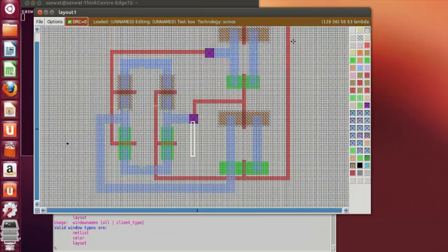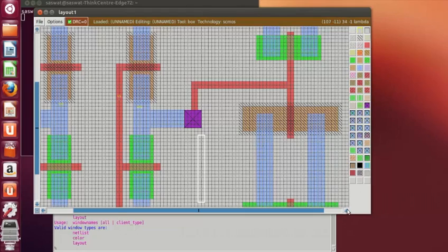Okay, this is connected to this gate. Actually, B is connected to this gate. B bar is connected to this gate. The opposite gates are connected. Then A is connected over here and A bar is connected over here. The output is obtained from these two drains.